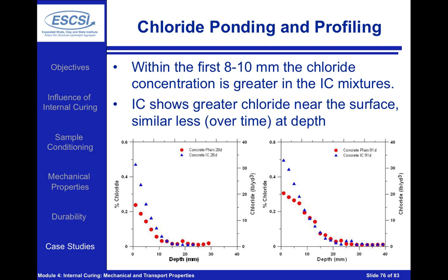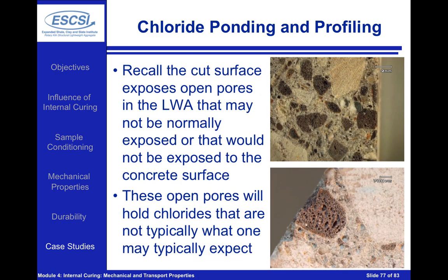However, as you get further away from the surface, getting down toward where the reinforcing bar is, what we typically see is a lower amount of chlorides, and at later ages we'll actually see that this becomes even less than a plain concrete in the overall system.